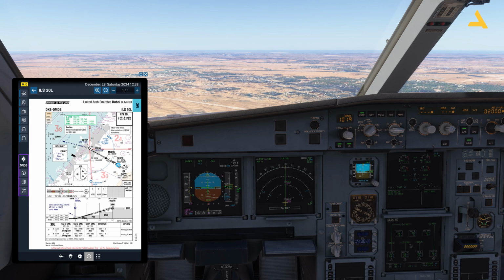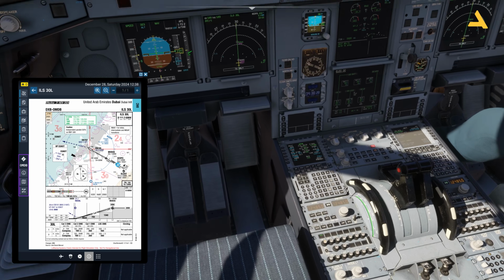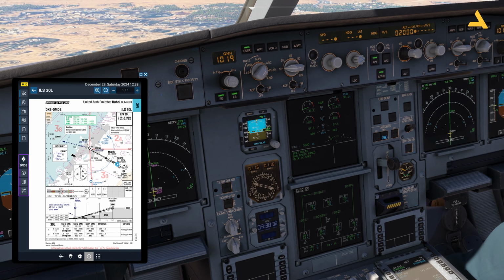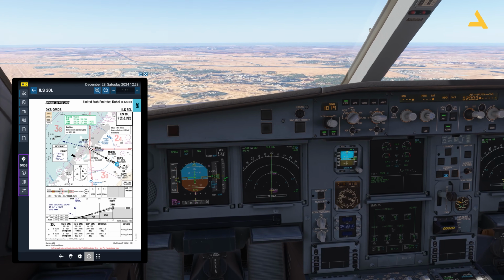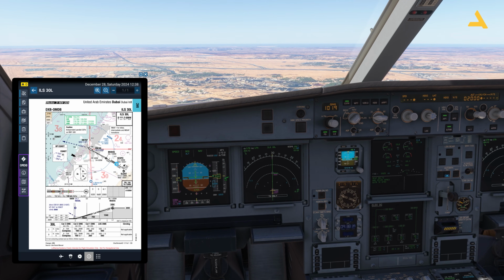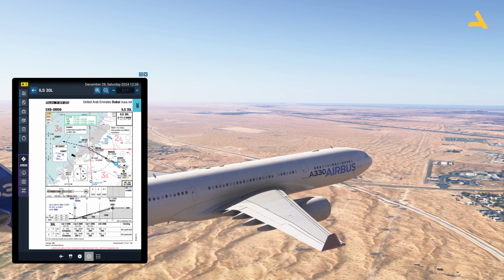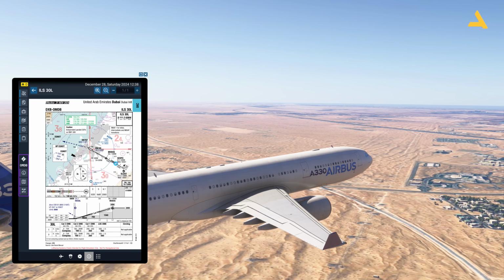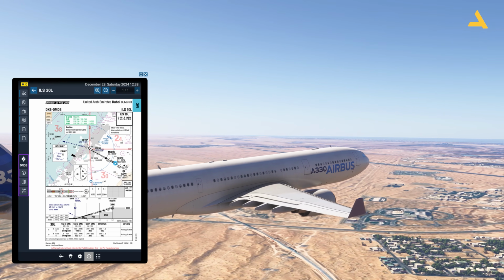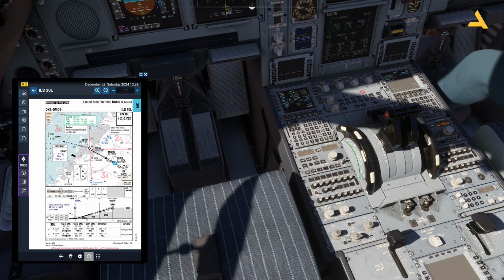Now I can disengage the speed brakes. I can arm the ground spoilers for the landing, and I can set the auto brakes to medium. Actually, these speed brakes or the ground spoilers, they're on the wings. So during the landing when I activate the reverse thrust, they will also come into action, which provides some support in reducing the speed of the plane.